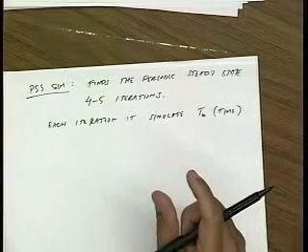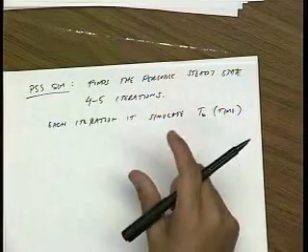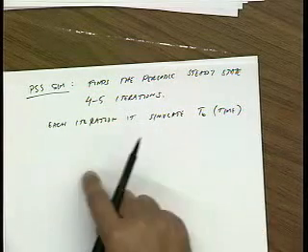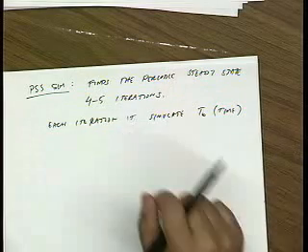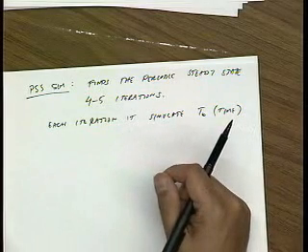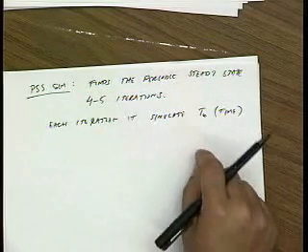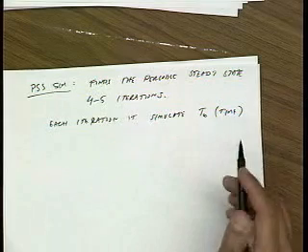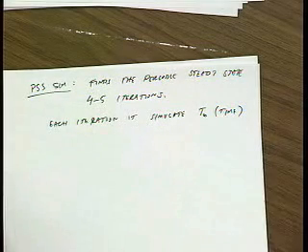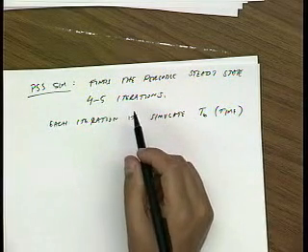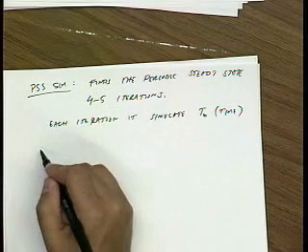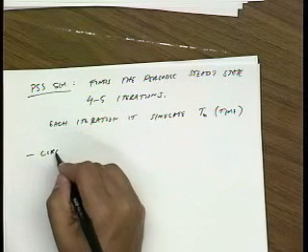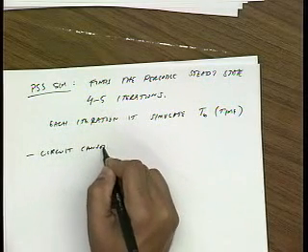Now that's really powerful, right? If we could use this information, we only need to do about 4 or 5 periods, as opposed to, let's say, 10,000 periods that we talked about before. The reason it can do this is, let's say PAC. Actually, before I get to PAC, let me just say a couple things here. There's a couple of conditions for PSS to converge. So the circuit cannot be chaotic.